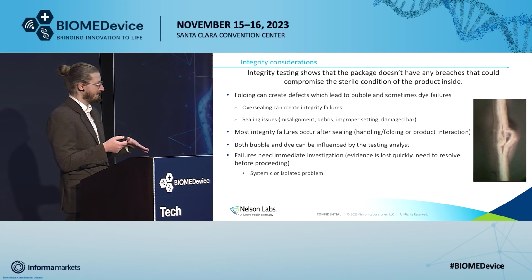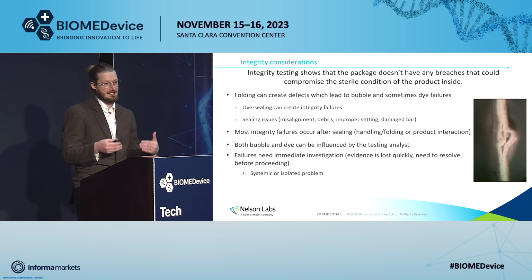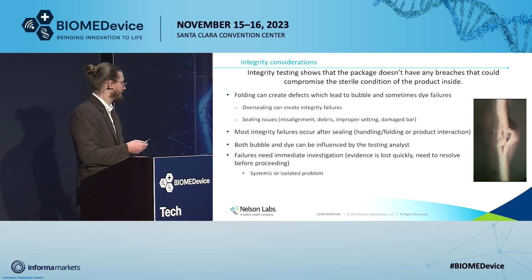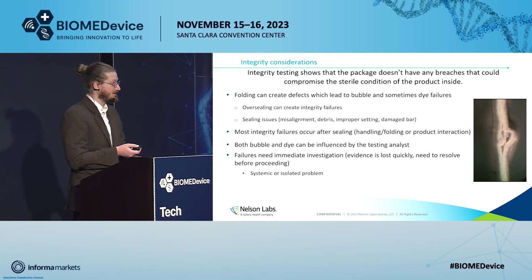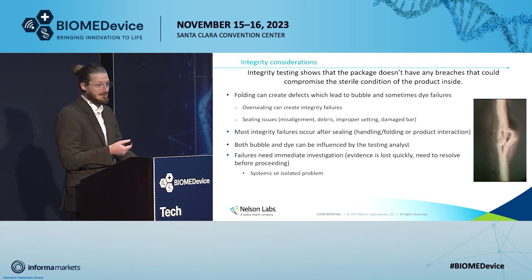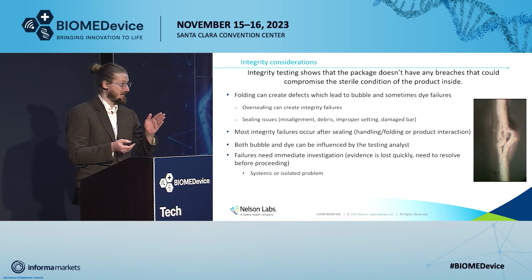Bubble and dye testing can be influenced by the person performing the test based on their technique. So it's important to have good technique and a nice validated process that is understood. For when you do encounter failures, you usually have to act pretty quickly to understand perhaps why they came about in the first place. Specifically with dye tests, the dye will wick straight through a channel if there's a channel,